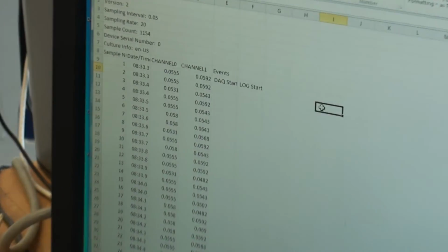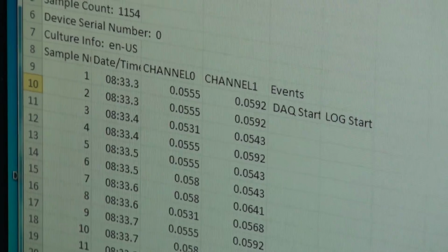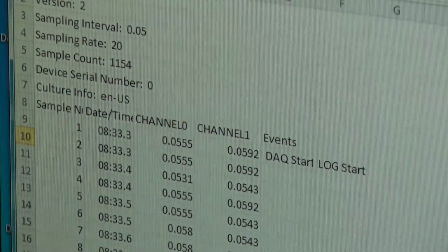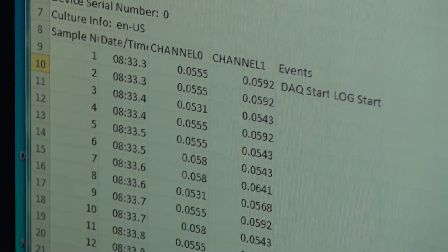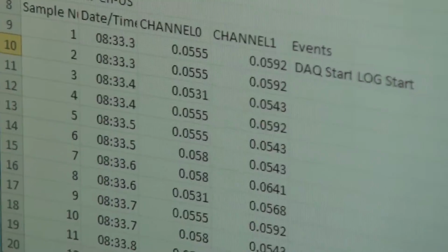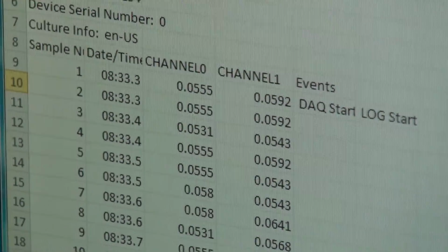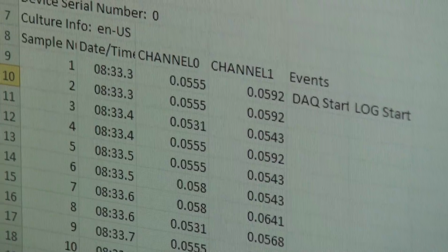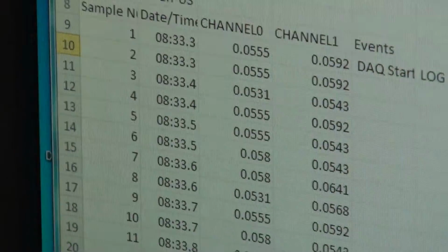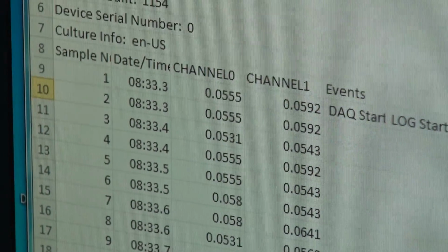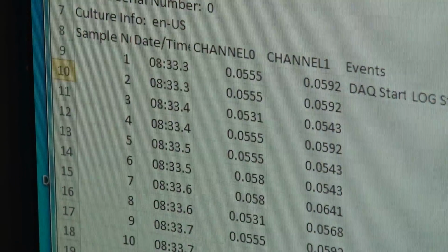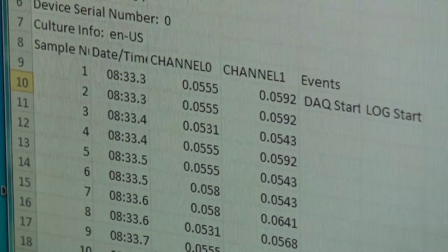What you're seeing on your screen here is one of the files that will be available to you in Sakai. There's a total of 9 files available there, one for each of the materials and feeds. What these give you are the horizontal and vertical force as measured as we conducted the experiment. To get your actual horizontal and vertical force number, you're going to want to take an average of the appropriate column. When you're doing that, make sure you cut off any data that seems to be false at the beginning and the ending of the run, as the machine may not have been contacting the material.